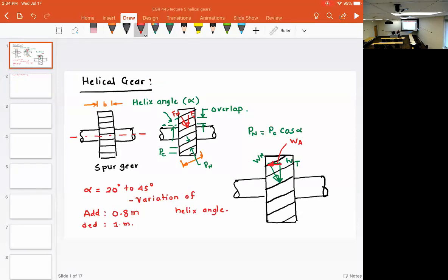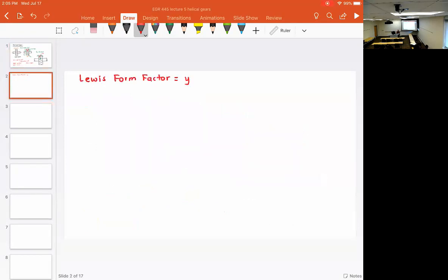Every gear will have different addendum and dedendum, right? Like the table is shown. Different materials will have different addendum? No, different material gear proportions will be the same. Different materials will not have different addendum or dedendum. The geometry of the gear would be the same, but depending upon the different material, the torque transmission capacity of the gear would be different.